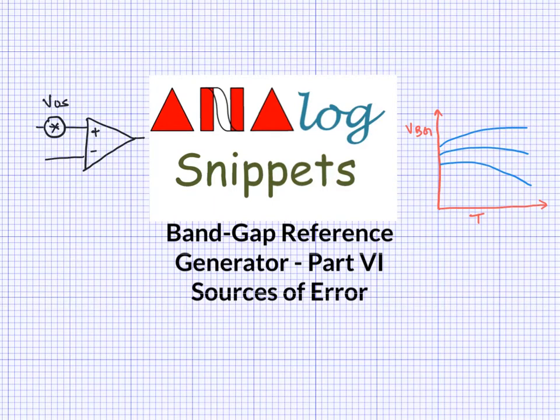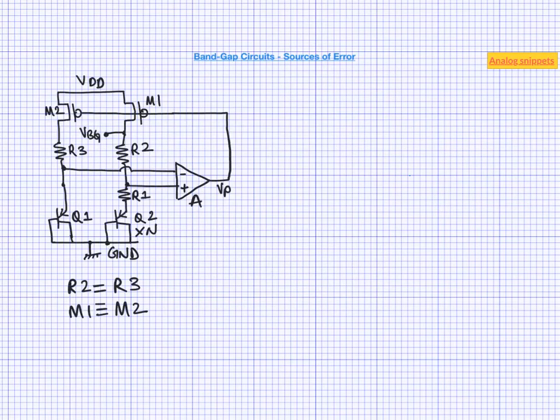In the last few videos, we have been looking at bandgap circuits as a means of generating rather accurate on-chip voltages. Like any other circuit, bandgaps also have their own sources of errors. So in this video, we will look at some of the more important sources of error in the bandgap circuit and some circuit techniques to minimize those errors. Let's begin with reviewing this bandgap circuit.